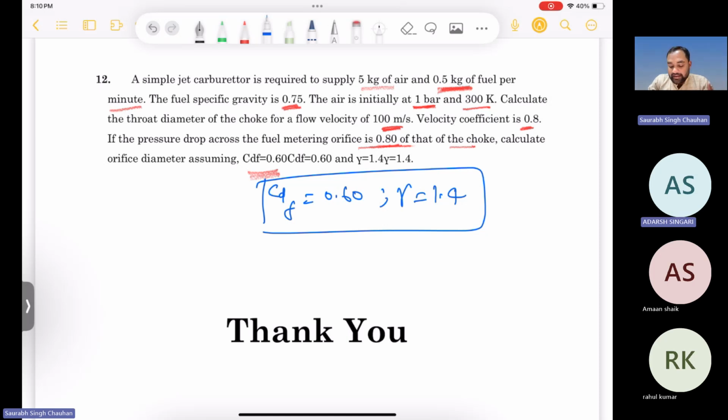So depending on that, there is some map. Map means basically at this RPM, at this load, if you run on battery, it will be better. And at that particular load and RPM, if you run on engine, that will be better. So there is some optimization. And other things as well. For example, when you are applying brakes, how do the brakes work? Brakes convert your kinetic energy into heat. But in electric vehicles or hybrid vehicles, they use regenerative braking, so the kinetic energy is stored as power in the battery. So a lot of technology is used.